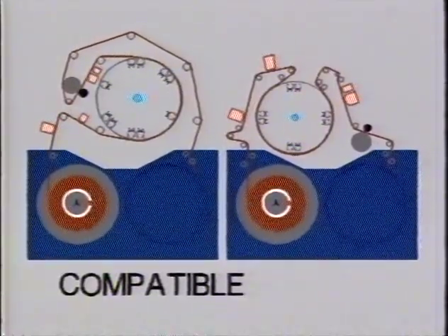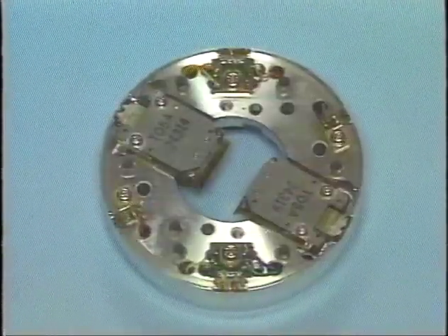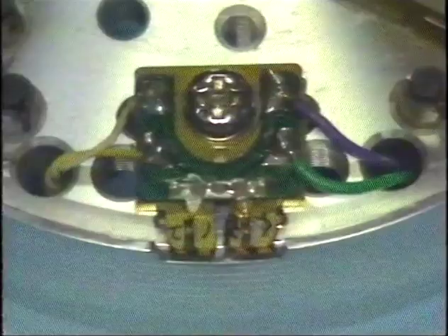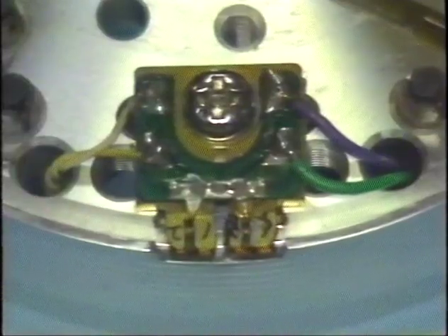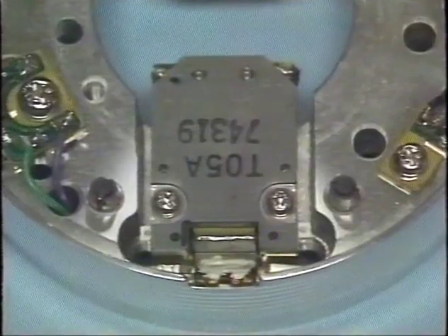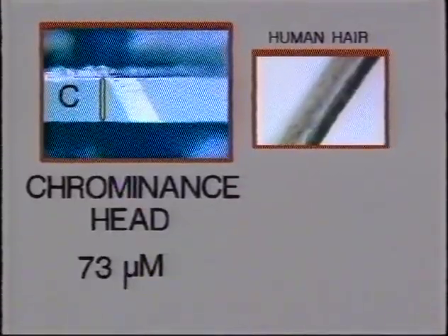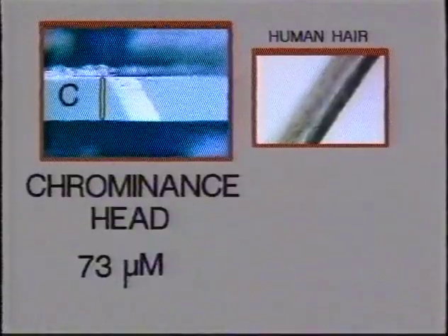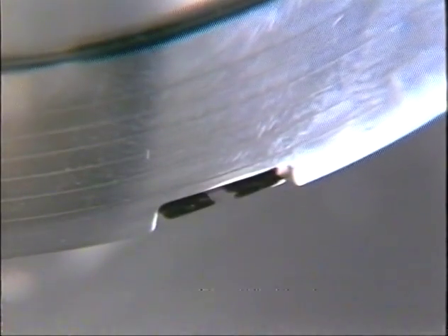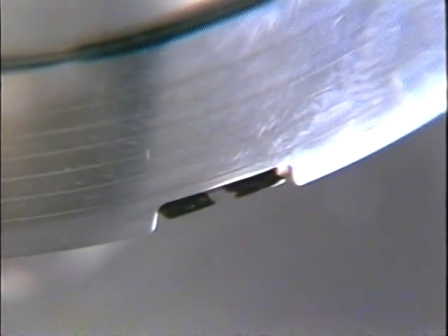The head drum itself requires further explanation. Here is a BBW75P drum removed from the machine. Here are the record playback heads, the arrays and dynamic tracking heads. The luminance head is 86 microns and the chroma head 73. Remember, it is this dimension that causes the track width. The dynamic tracking head, or DT for short, can move vertically so as to follow tracks at different tape speeds.